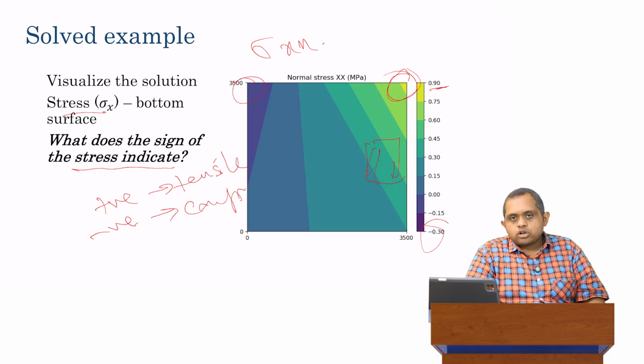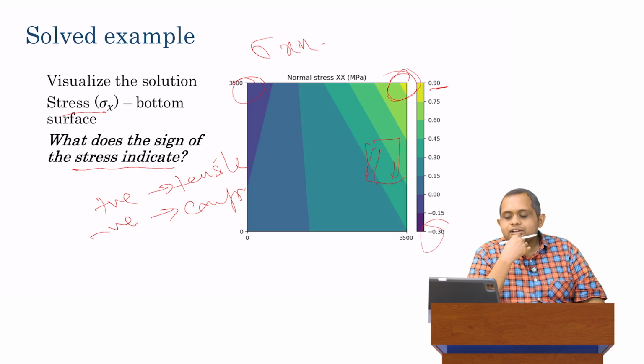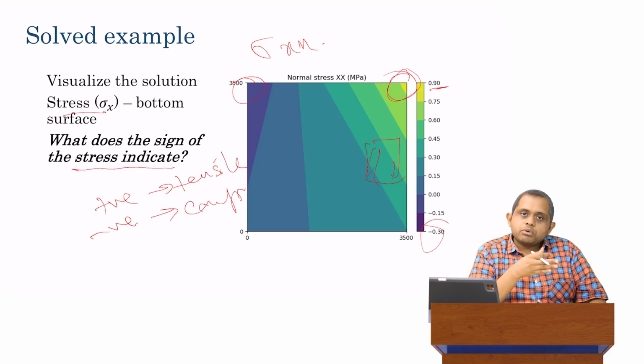And generally, as we talked about earlier, for rigid pavements, we are actually only concerned with the tensile stress. The concrete is very, very strong in compression, except for the Freiberg analysis with dowel bars. With that one exception, we don't really care about the compressive stresses. We do care about the tensile stresses. And that was the logic by which the developers of ISLAB chose to set the convention such that a positive stress indicates a tension.